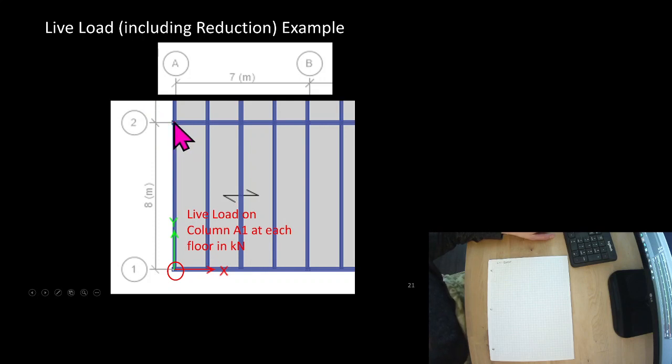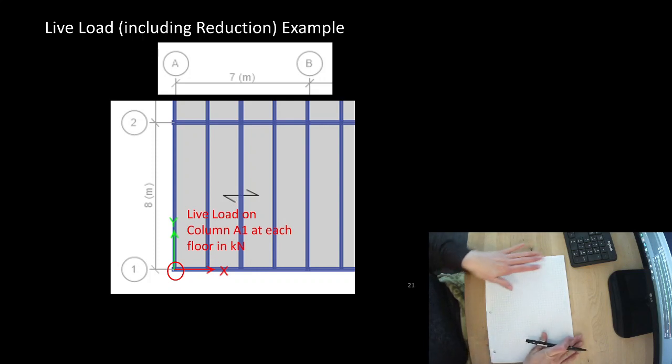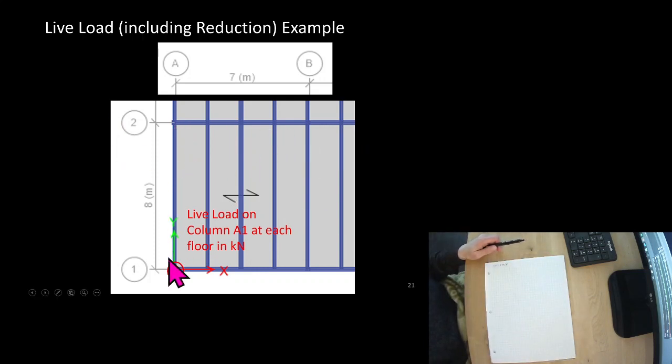If we looked at that 3D ISO, we could see it. So this column here, it's exactly like our table. We've got 4 columns, and you know intuitively, you can't see it, the camera's pointing down, you know that a table with columns here and here and here, that if you have a weight on this, that a quarter of it's going to go to each column. Meaning that this zone here, a quarter of it is going to go to each column.